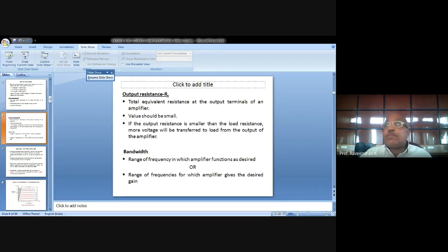And to make the operating point independent of the gain of the transistor used. If these conditions are satisfied, then the operating point will always be kept well within the active region of operation for a stable IC and VC of the transistor. IC and VC mean collector current and collector emitter voltage. That is, the collector current and output voltage of the transistor are stabilized.